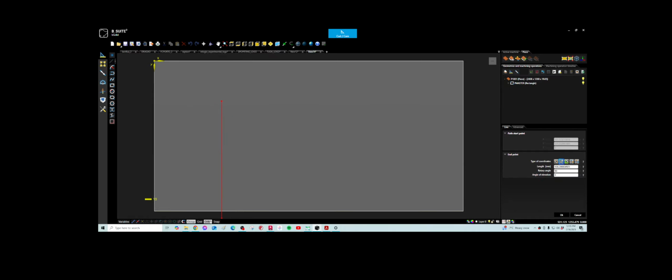If you want to change that, you just go here and select ortho, and then you can go any angle you want. See, if you look at here, rotary angle, you'll see that it goes to whatever you want, right? But I like to use ortho in this case. So I selected a random point, I make a line, I put a tool there, and done.